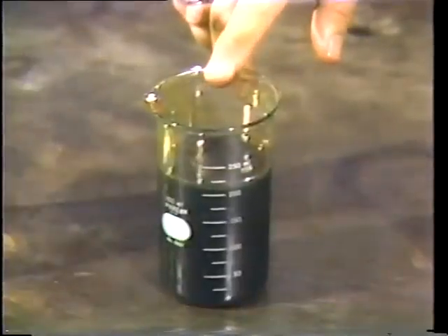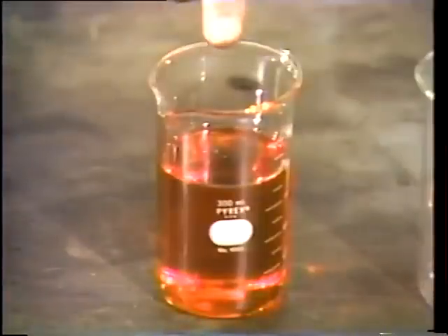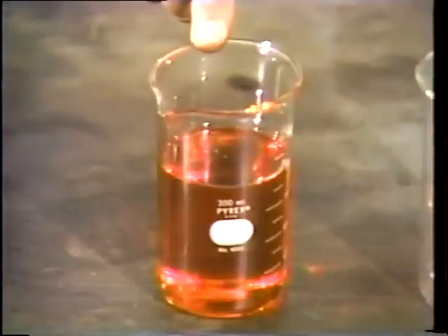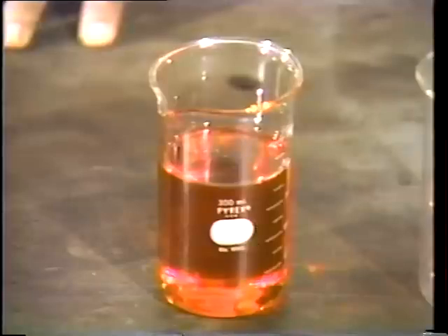Mineral oils are petroleum products and come from refined crude oil. Most of the lubricants you'll work with in your plant will be mineral oils. Because of their stability, mineral oils perform their lubricating functions under high temperature and pressure. Synthetics are man-made lubricants. They're manufactured from a mineral oil base or from other non-petroleum-based substances. We'll talk about some of the other substances a bit later.